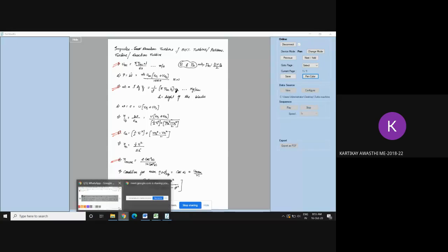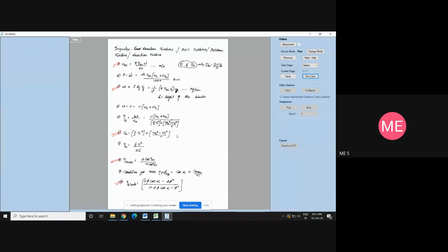Those are the changes we are seeing in reaction turbine compared to impulse turbine. This you all know, because efficiency there will be different, here it will be different. Energy available there is different, here it is different. M dot, this is the general equation, that is rho into Q. Q is A into velocity, area into velocity. Area is pi D mean H into VA.